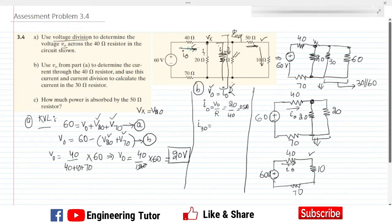As we know, we have already found it here. So now the equivalent resistor is 20, and the other one is 20. These two are equal resistors. So the current here will be divided into two currents. One current will flow here, the other current will come here. As the two resistors are equal, this current will be equal for both, and this is now 0.5.